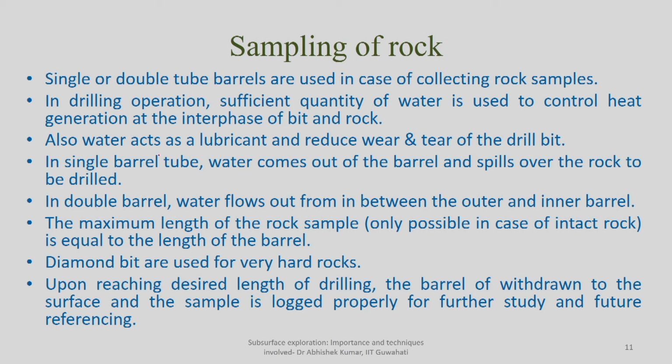So water will act as a lubricant, and it will reduce the wear and tear of the drill bit. So it can be used, in sufficient quantity. You have to continuously flow some kind of water there, which will reduce or control the heat generated at the interface of the drill bit and the rock. And the second one, it will be used as lubricant and reduce the wear and tear of the drill bit. So that's why water will always be circulated through it.